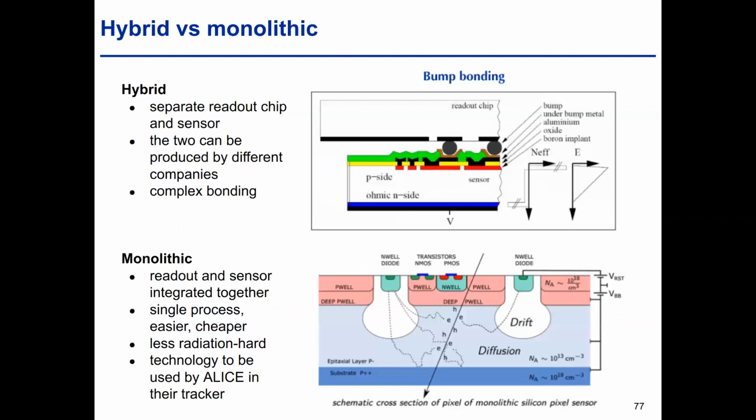I will just briefly mention that what I described is what is called a hybrid pixel module, because it puts together two different elements. This PN junction, what we call the sensor that will be biased, and then a dedicated chip that is used to read out the signals, okay? And since I mentioned that the connection between the two is a critical element, you might wonder, well, can you just make them together from the start? And that's the idea behind the monolithic sensors, where essentially the readout electronics and the sensor are just designed together in the same piece of silicon, okay?